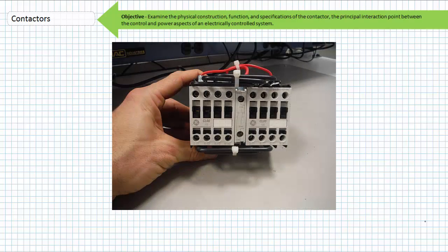Contactors and reversing starters work in pairs to run a motor either forward or reverse. The mechanical movement of the armature and a mechanical interlock between the paired contactors serves to protect systems requiring mutual exclusion between the two states. One would never attempt to rotate a motor both forward and reverse simultaneously. Not only does it not make sense, such an action would constitute a phase-to-phase event in the case of three-phase AC, an exceedingly dangerous and destructive event.